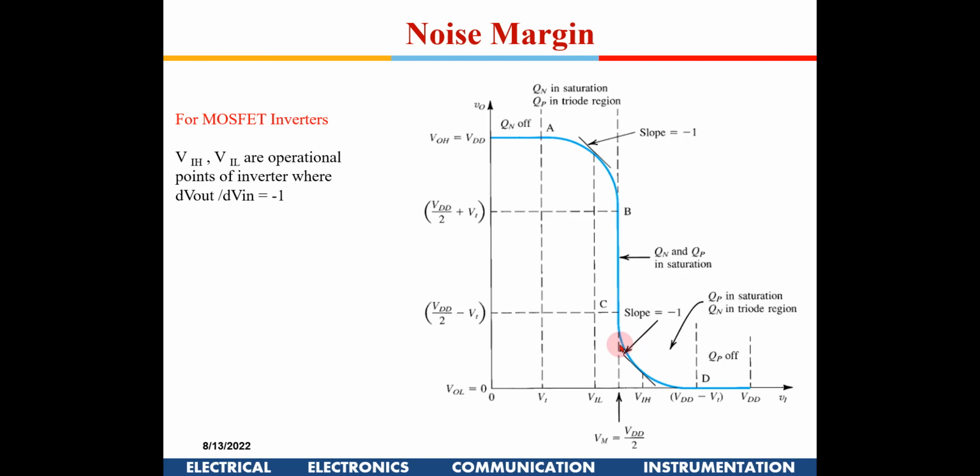So you have Schmitt triggers and all, where you have a hysteresis curve. For the positive going, you push it towards the right, and for the negative going VDD, you push it towards the left. So that aspect will be covered in your advanced VLSI classes. Okay, for the time being, we have a single curve, and we have defined noise margin, and we'll move ahead and see how things look.